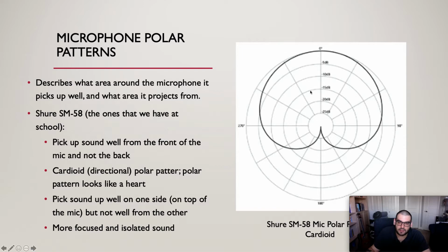So remember, with dynamic microphones, sound is only coming from one side, not from all around. Just like a vocal microphone. You don't want it picking up sound from behind you or in front of you. If your monitor's in front of you and you're singing into the microphone, you don't want the sound coming out of the monitor to come back into the microphone. So it's hitting from the bottom of the microphone itself. And that's why, when we see here, the directional pattern, the polar pattern, the cardioid pattern, is only from the front of the microphone.